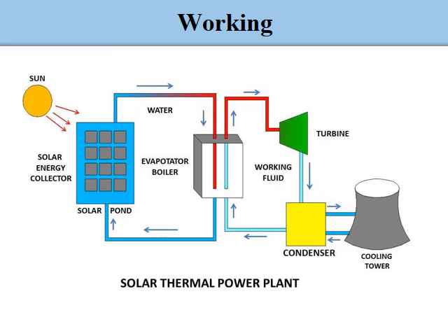In the evaporator boiler, the high temperature working fluid transfers heat to the low temperature working fluid. So vapors form. These vapors are further used to run the turbine. The turbine is also connected with the generator to produce electricity. In the turbine, an expansion process takes place, and due to the expansion there is cooling. So the working fluid goes into the condenser.